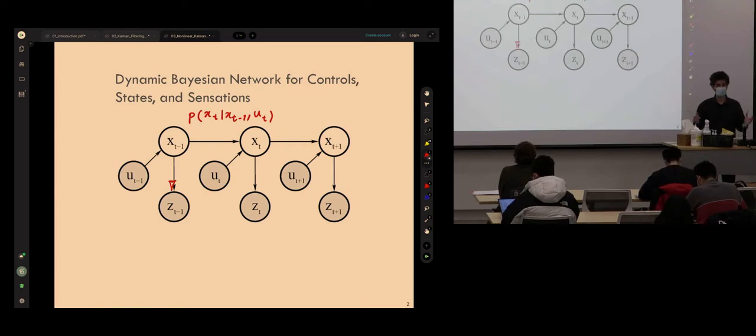So conceptually, what this tells us is that it is a probabilistic model that helps the state transition from time step t minus 1, or k minus 1, we're talking about discrete time steps, to time step k using a known deterministic command, right? You signal, for example, move forward for a delta t of 0.1 seconds. The robot will move forward as much as it can, and then maybe you have a model to predict where the robot will be.